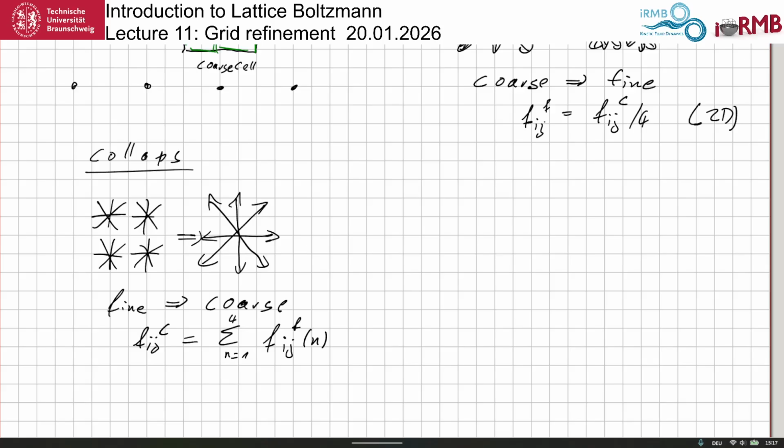So, and in addition to this, you use acoustic scaling. This is something that they had been using from the beginning. This is also a big difference from most of the other CFD solvers. So what you do is you keep delta x by delta t constant.